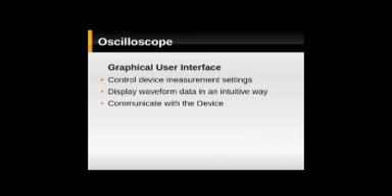The oscilloscope has a very simple graphical user interface which allows the user to control how the device measures signals. The user can control how many channels are active and the resolution of both amplitude and time. The channel, edge, and level can be specified for the sample trigger window. On the oscilloscope graph, the user can use the grid to observe time and voltage measurements. Cursors are provided for more accurate readings. The GUI receives data and sends commands to the device over a standard USB COM port.